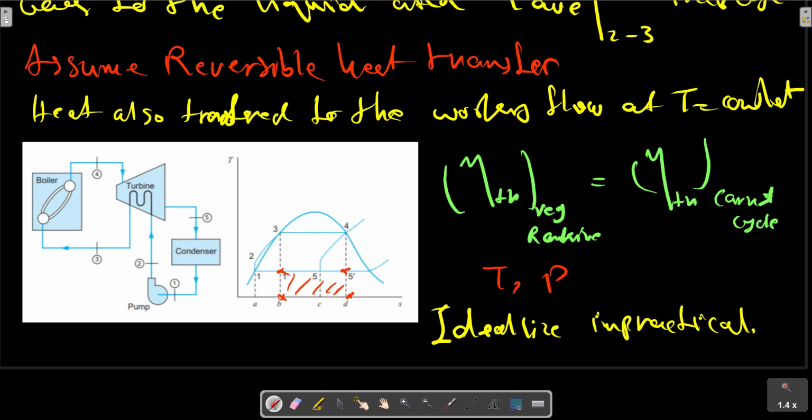First, it would be impossible to effect the necessary heat transfer from the vapor in the turbine to the liquid feed water. Furthermore, the moisture content of the vapor leaving the turbine increased considerably as a result of the heat transfer. The disadvantage of this was noted previously.